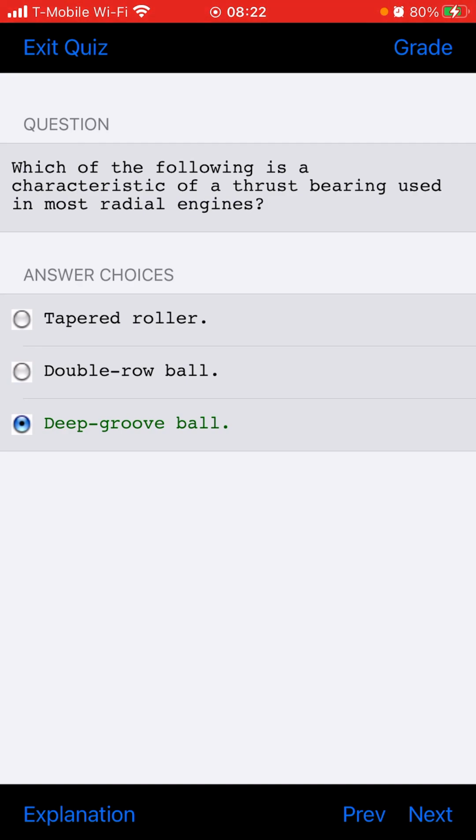What is meant when it is said that an engine part is within serviceable limits? A part that is within serviceable limits will not likely wear to the point of causing engine failure within the next time between overhauls.